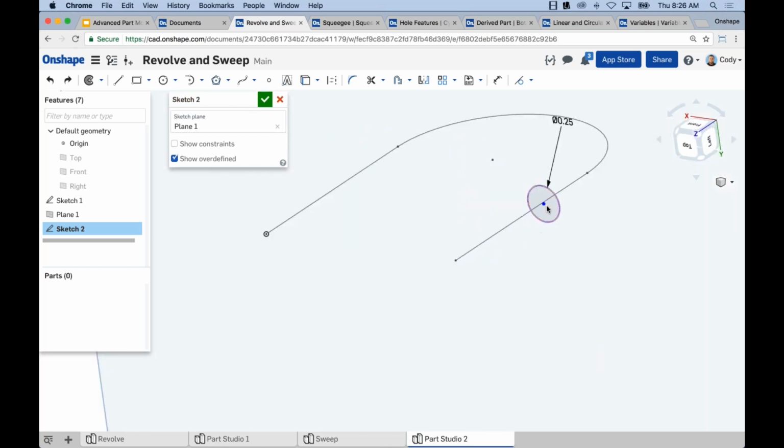Now, in this example, it's very easy for me to just left-click the point, and make the two coincident. Coincident, as I mentioned, is one of the ways that you can do that. Now, you may not have a point here. What if this line continued on for a long period, or what if it was some other scenario where I wanted to attach the point to the line? That's where you would use the pierce constraint, right? Where this line pierces the current sketch plane, it will attach your point. So just realize the coincident or the pierce constraint are necessary in order to attach your profile to your path.